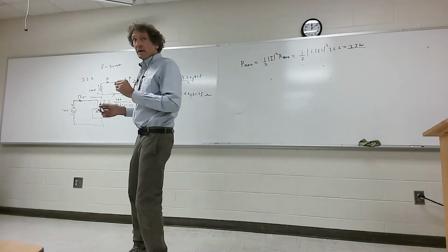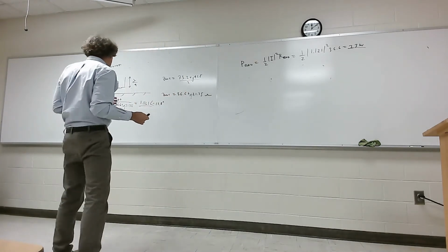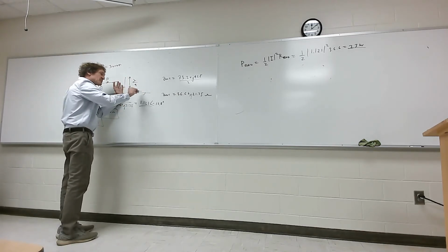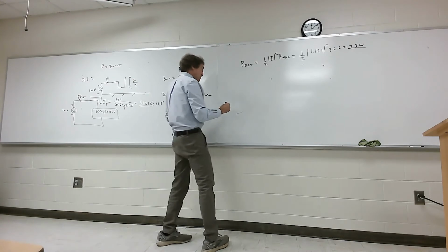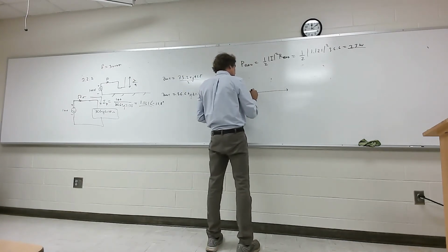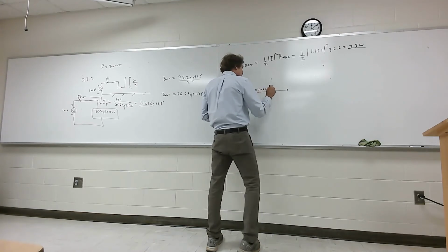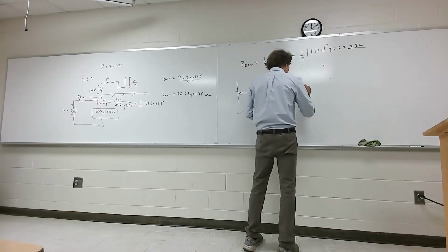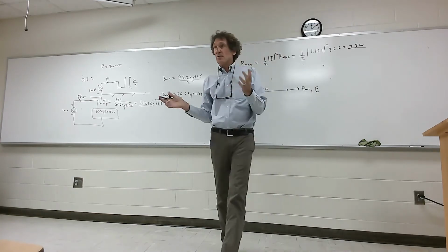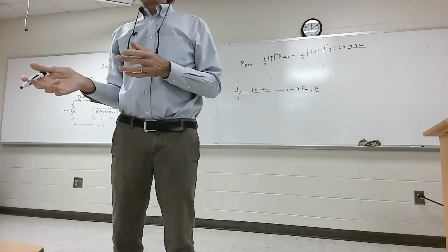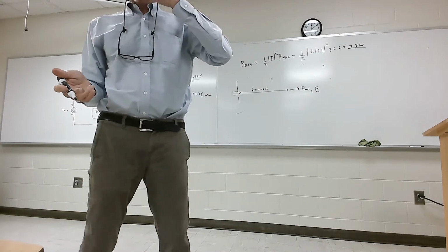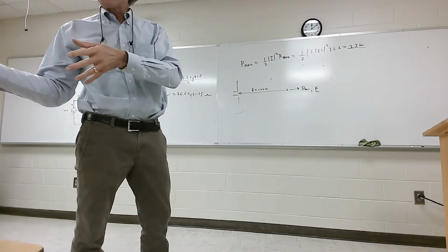Yeah. All right. So if this is a quarter wave monopole, and we're exactly at 90 degrees, it's right on the ground. Here's what the dipole looks like, right? We would be out here, did you say 100 meters? Yes. 100 meters away, they want the power density, PAV, right? And they want the electric field. Now, this is up to you how you get it. I usually just go for the power density, but we can do the electric field one using the electric field equation that's given.